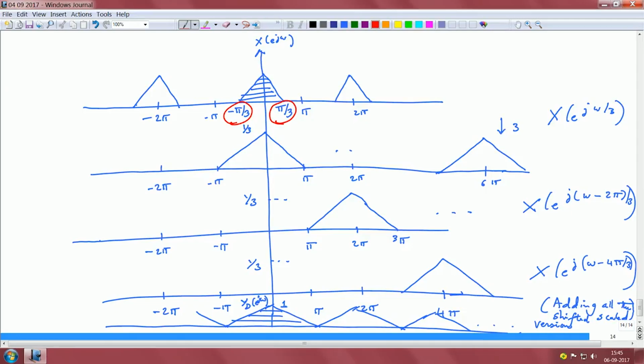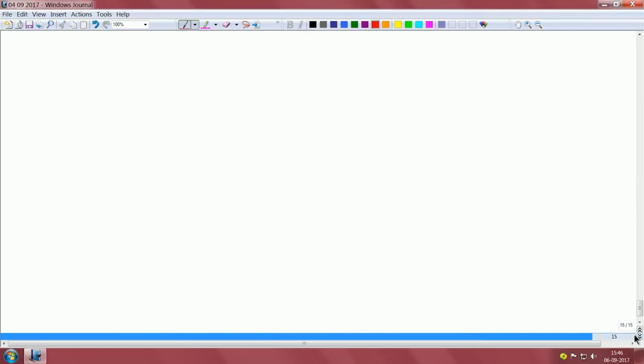If you stretch and the spectrum goes beyond the minus pi and the plus pi points, there would be aliasing, and if there is aliasing you cannot reconstruct the signal without doing any other operations. If you just invert, you will not be able to get rid of this aliasing error. So this leads us into an important condition to avoid aliasing, which can be succinctly stated as follows.